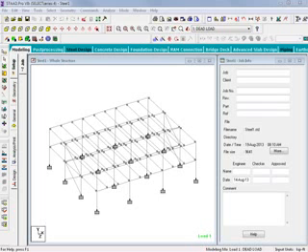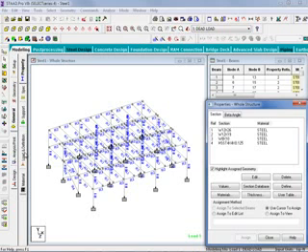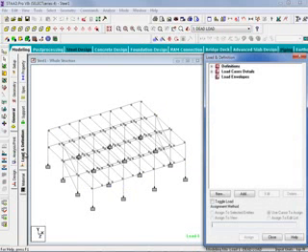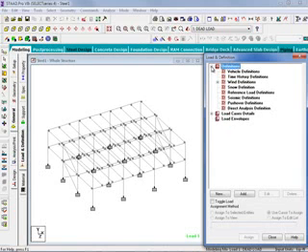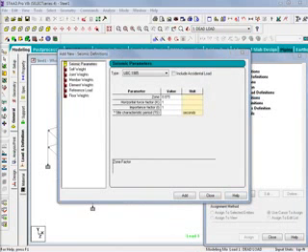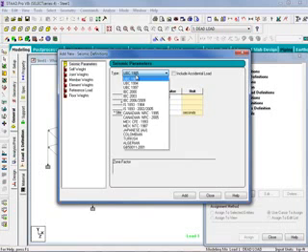To create our seismic load definition, we will open our STAAD.Pro model, click on the General tab, and then select the Load and Definitions sub-tab. We will then expand the Definitions group, select the Seismic Definitions item, and then click Add. In the Add New Seismic Definitions dialog, we can select which building code we would like to generate our equivalent lateral force procedure seismic loads according to, and we do include several American and international codes. For this training course, we will select the IBC 2006-2009 code.